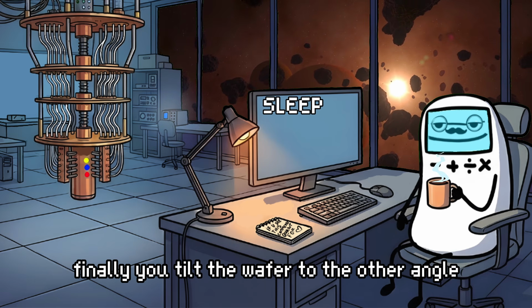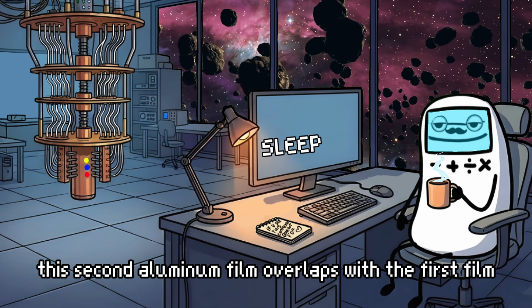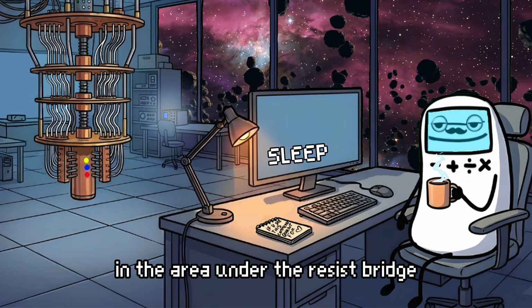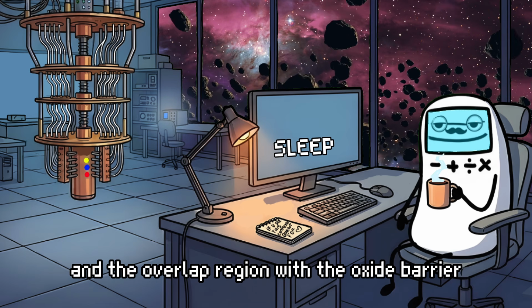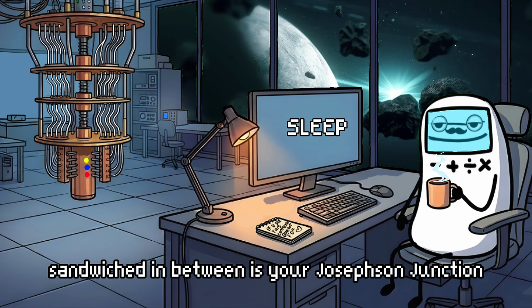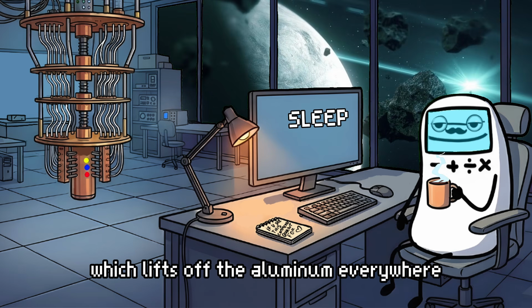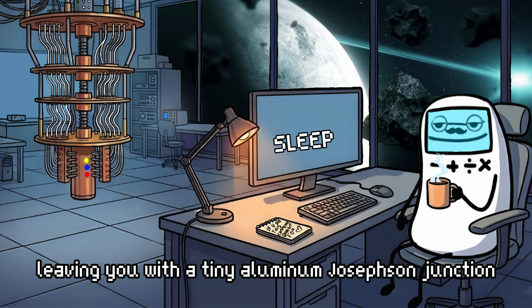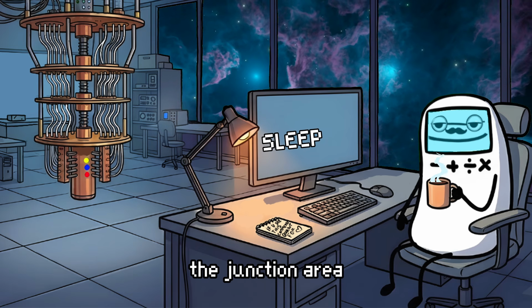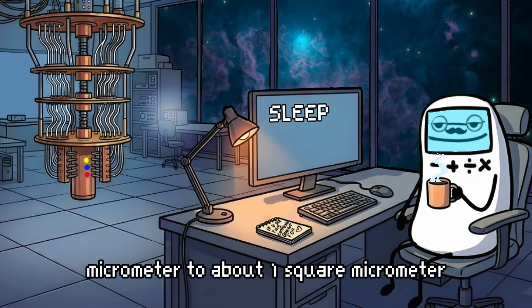Finally, you tilt the wafer to the other angle and do a second aluminum evaporation. This second aluminum film overlaps with the first film in the area under the resist bridge, and the overlap region with the oxide barrier sandwiched in between is your Josephson junction. Then you strip the resist, which lifts off the aluminum everywhere except the junction area, leaving you with a tiny aluminum Josephson junction.